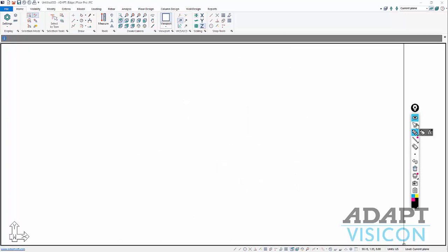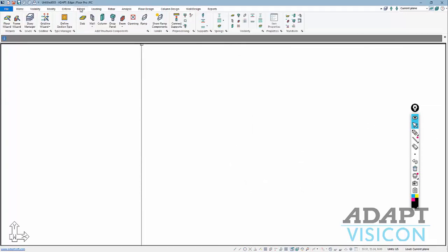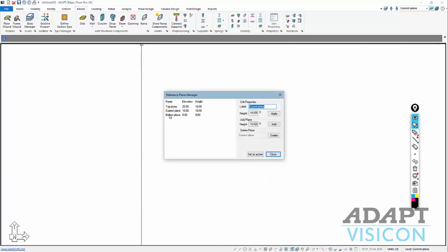So let's go ahead and begin with that modeling. I'll go to the story manager to start developing our model. We're going to use this as the base of the pile. So we're going to call this base underscore pile. And I'm just going to add a bunch of levels in here. Okay, this will be 5 feet. We're going to just change the height of these. These will all be 5 feet.